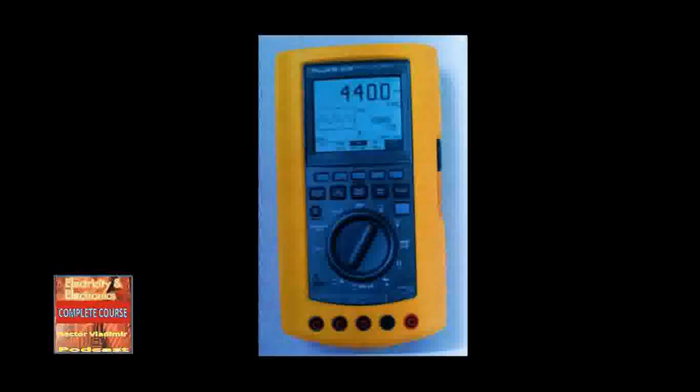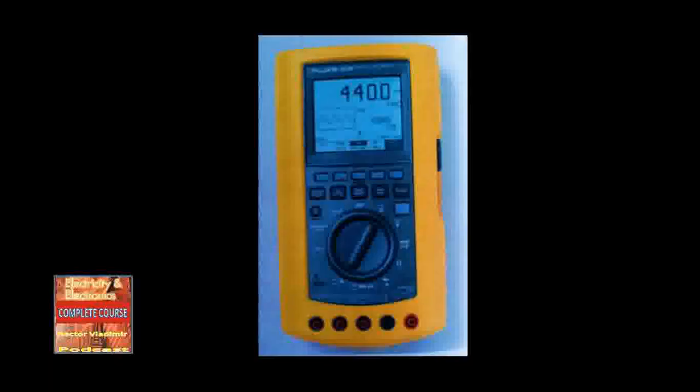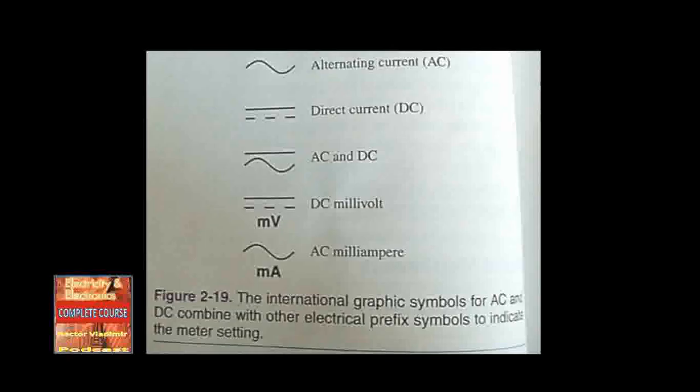Some digital meters have an auto range feature. This means that it is not necessary to determine the range to select when using the meter. On these meters, this function is done automatically through the internal electronic circuitry. Figure 2-20. Resistance reading used in a DMM still requires you to disconnect the circuit from the power source to prevent damaging the meter. Figure 2-18, at the lower right of the selector switch of this DMM is a setting to test diodes and capacitors. Figure 2-19, the international graphic symbols for AC and DC combined with other electrical prefix symbols to indicate a meter setting.